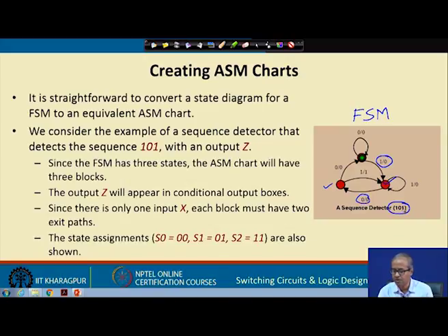and if you get a third one, you move back to this state with the output 1. That means, you have found out this sequence. Now, this third one means there can be an overlapping sequence also like this. The third one means you have detected a 101 here, but it can be the start of the next 101. So, you move back to this state. So, there can be another 0, another 1. So, this second sequence can be detected again, right. So, from here if it is 0, that means you have to start from the beginning, you go back here, right. Now, let us see.